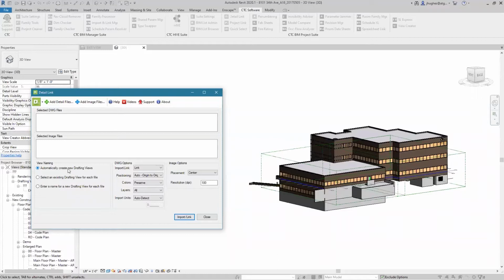But oftentimes you're going to get details from a manufacturer. For purposes of this demonstration, just yesterday I thought off the top of my head, well, let me run to Siplast and see if they've got some roofing details that I could snag. And sure enough, it is pretty easy to grab a bunch of DWGs from them. So if I wanted to add those into this project here, if we wanted to entertain this being a Siplast roof and start looking at those drafting details, then what I can do is choose Add Detail Files up here at the top.